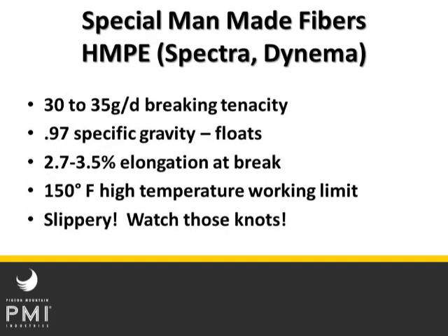HMPE ropes, Spectra and Dyneema are examples of those. 30 to 35 grams per denier. These are ropes that are nice and strong. They do float. They have a specific gravity of typically 0.97, which is really great. And so if you want a strong water rescue rope, this would be the one to use right here.